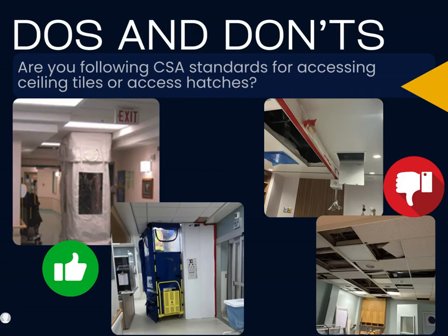Do you know how to access ceiling spaces appropriately? Preventative measures are necessary during ceiling access because disturbing ceiling spaces, even for short and minor tasks, can release dust and contaminants that pose infection risks, especially in healthcare settings. Reach out to IPC before you begin work to discuss the scope and the risk group for the area.